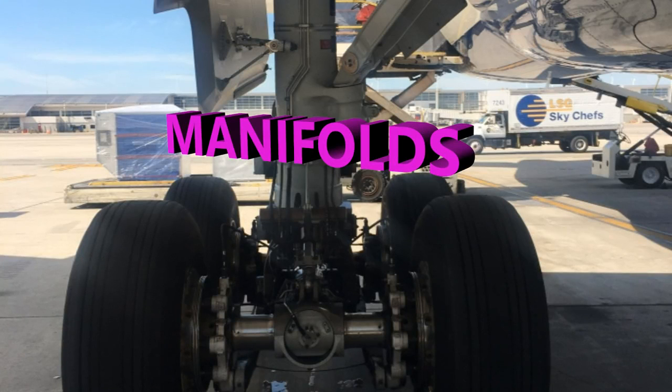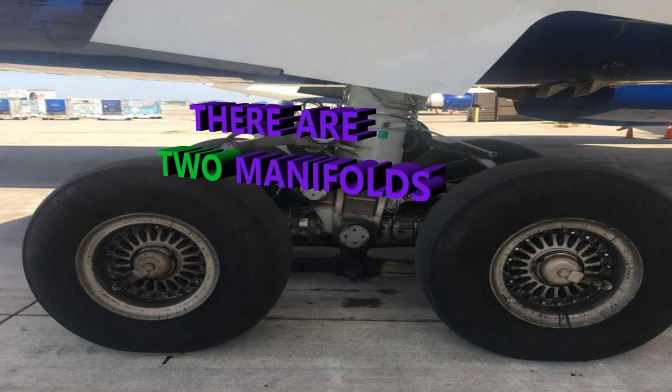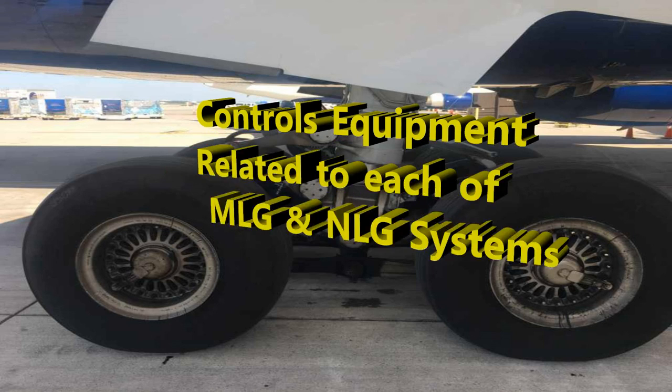Let's go ahead now into manifolds. Okay, what manifolds do we have? Well, there are two manifolds that are used. We have one that's going to be controlling the nose landing gear, and the other one's going to be controlling the main landing gear, and then just controlling all the equipment related to each of those. Okay, and then just know the main landing gear is using the green hydraulic supply. Your nose landing gear is using the yellow.